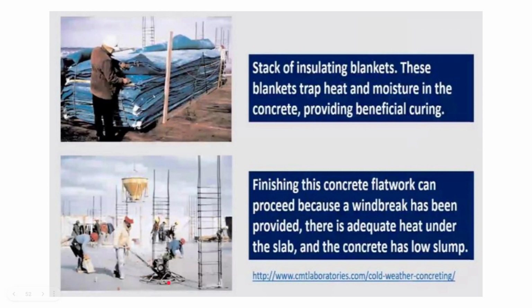And here, inside, heat is there under the slab, okay. Finishing this concrete, this is basically flat work. So the concrete flat work has been finished, and it can be proceeded using a windbreak, okay. Some facilities have been given which can break the flow of wind, and there is adequate heat under the slab, and the concrete also has low slump, okay. Low slump will result in quicker hydration and quick stiffness, okay.